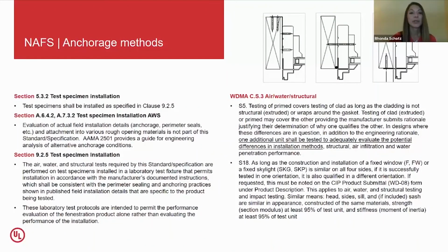Per NAFS, when trying to qualify multiple anchorage methods like installation masonry clip, screw-through frame, or nail fin, section 9.2.5 note is critical. The laboratory test protocols are intended to permit the performance evaluation of the fenestration product alone, rather than evaluating the performance of the installation.